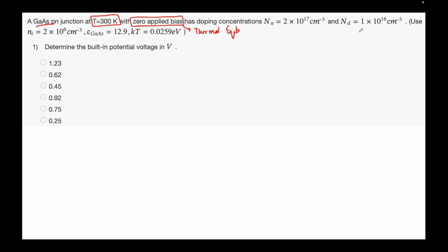Yes, you are correct, 1.5 times 10 to the power 10. Even if you don't remember the 1.5, just remember the order, because that tells you how many carriers are there. So for instance, for gallium arsenide, the intrinsic concentration is only 10 to the power 6, so it has 4 orders of magnitude fewer intrinsic carriers, mind you, than silicon. When we compare the materials, these things become important.